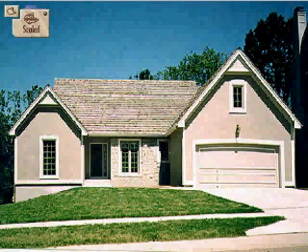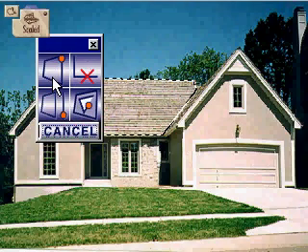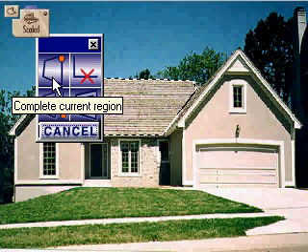To begin the outline, click the arrow on one corner to anchor it. Continue to drag and click the left mouse button around the perimeter to create your area. When you are through, right-click, then select one of the options on the menu. In this case, left-click on Complete Region.